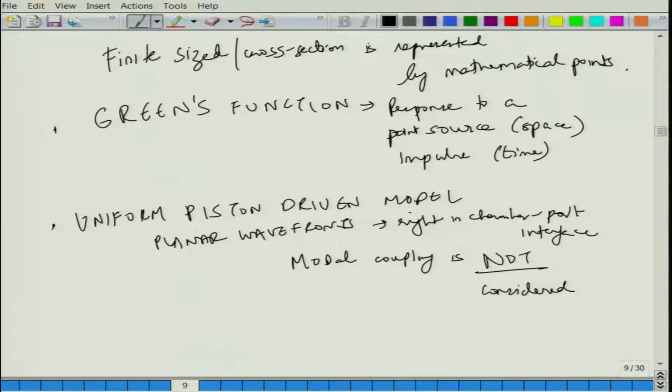So we are taking into account the pressure variations across the chamber over the surface area where the port is located, and using that to get the pressure response function of the impedance matrix parameters. We will compare this with the finite element results wherever they are available.